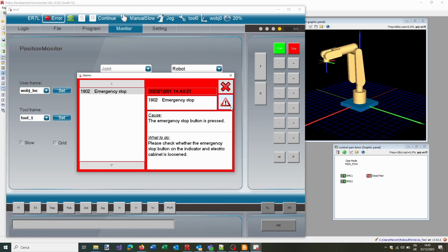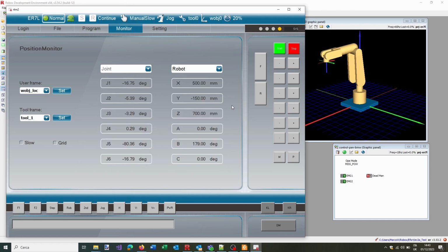Some of the most updated TPUs do not have these 2 buttons to close and solve, but just one of the 2 that will make both the fix. So just press it sometimes in order to be sure to reset all the alarms and go to the normal situation. Now, as we know, we can read here the operating mode of our robot.